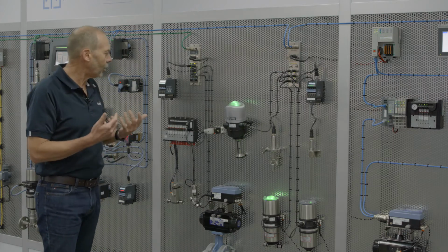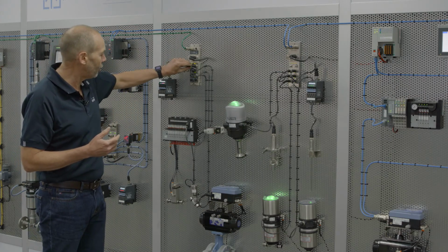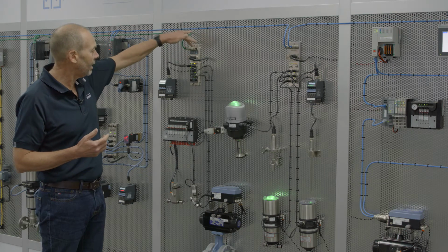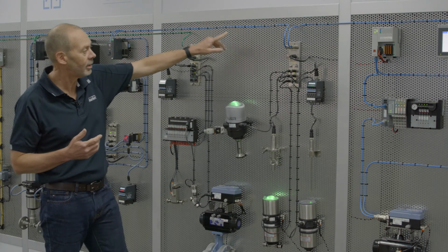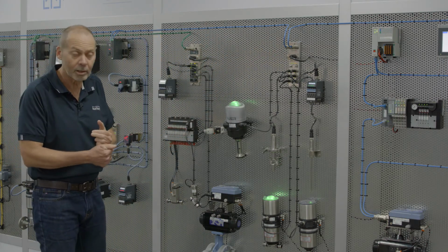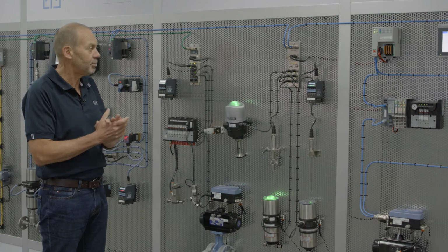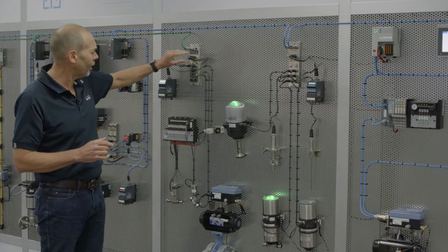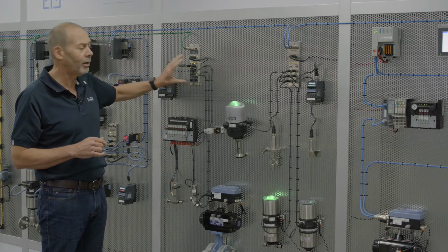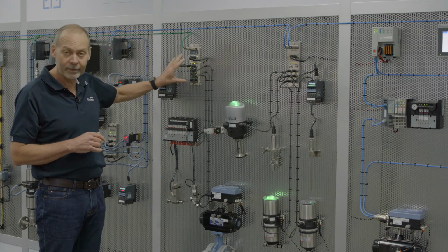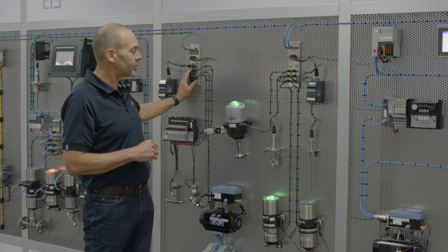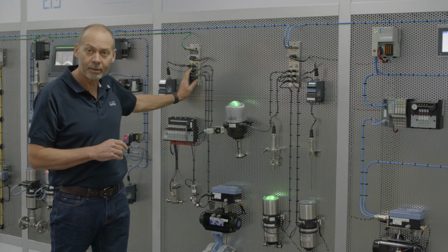A couple of the options that you can do with any of these ports: firstly, you have your Ethernet coming in and out, which means it can go onto a redundant ring topology, which makes it easy to put into the field. You have an additional power supply that can be brought into the modules, so you've got enough power locally to power whatever devices you've got installed. And both of these examples have 8 IO-Link ports.